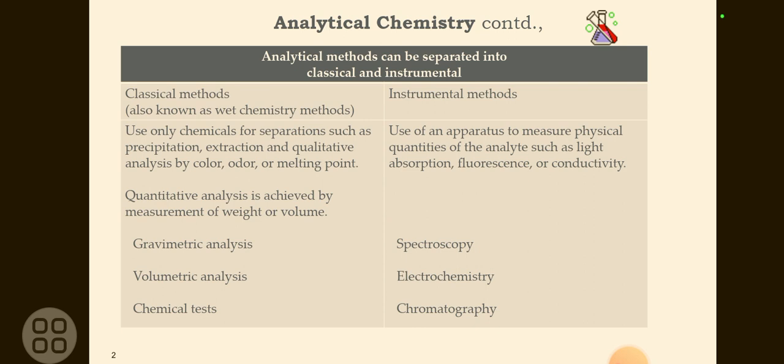So we will generate a method to identify in the cleaning solvent whether the material is present or absent. For that we will develop a method using the UV technique. Generally, for the KSMs and intermediates, we use a vessel in the process or manufacturing area. After using that material, we have to clean that vessel or reactor. So how will we confirm whether it is completely cleaned or not?